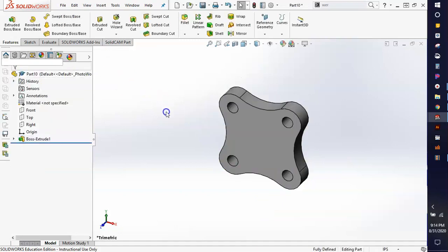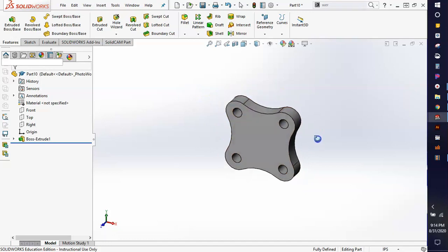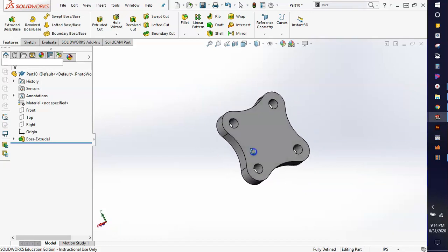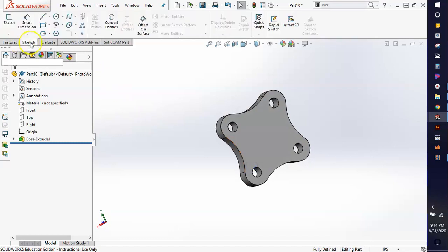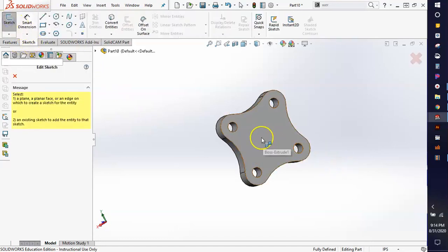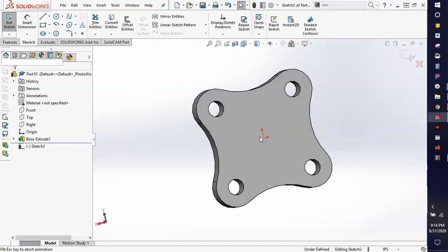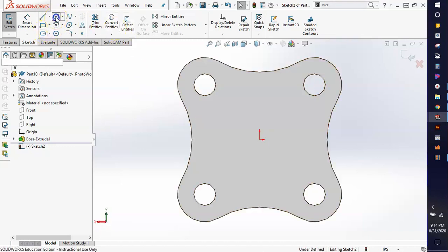Okay, so that's fine. Let's continue just to draw all the way back, and then we'll come back here and do these inside parts. All right, so I'm going to rotate around to the back, and I'll draw on the back side, which you could actually draw on the front side and extrude it through. It really doesn't matter. I'm going to hit Control 8.